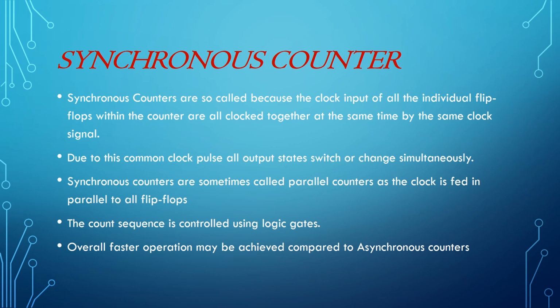And also, synchronous counters are sometimes called parallel counters because the clock is fed in parallel to all flip flops. So that's why they are called parallel counters. And also, the count sequence is controlled by logic gates. We will discuss this in the next tutorial where we will discuss synchronous counters in detail. Overall faster operation. Here the faster operation may be achieved because there is no delay. All trigger at the same time.